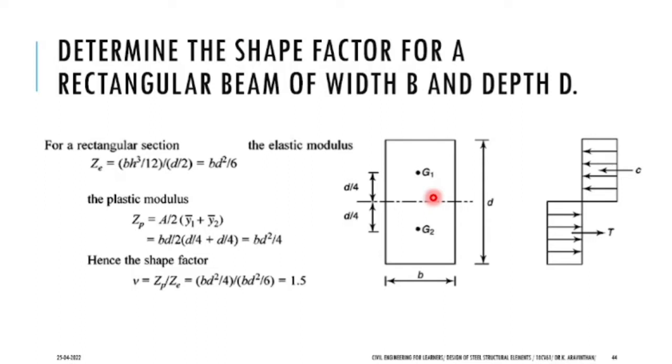Either for 0.8 or 1.2. For the 1.2 shape factor only, you have to construct your building. If you are constructing for 0.8, what will happen? It takes lesser load than the 1.2. The collapse will occur much earlier. So this is the advantage of finding the shape factor.